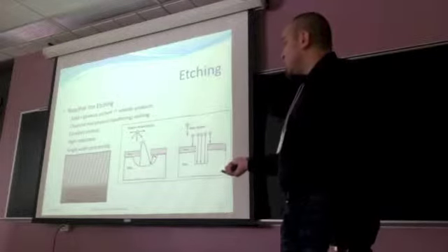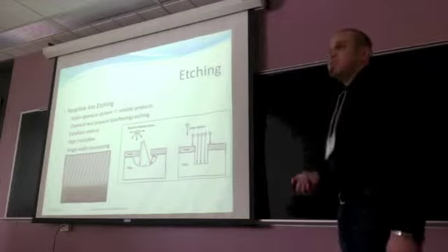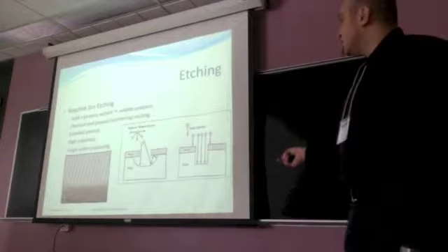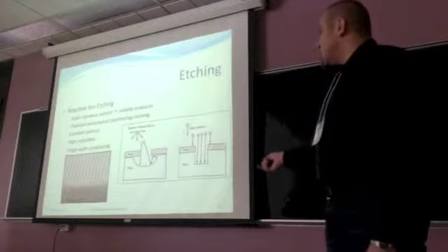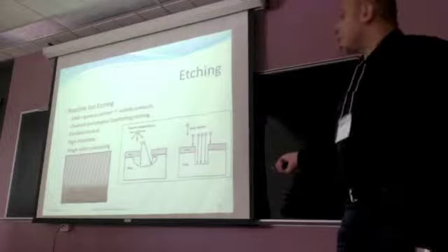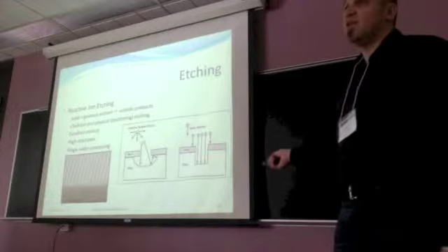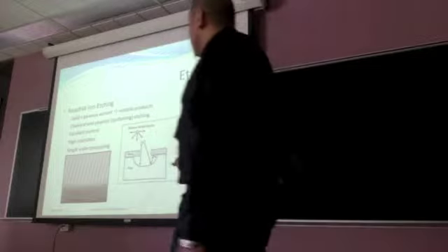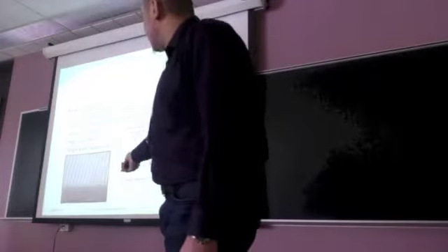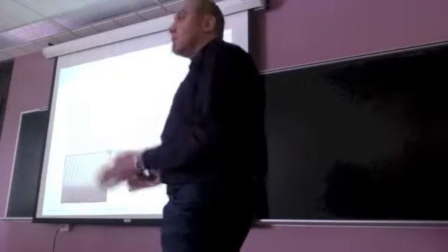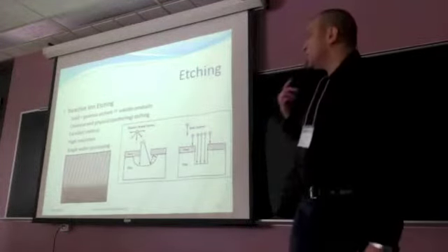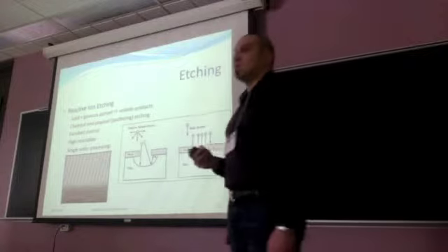And the physical etching is due to ion bombardment of the sample. And this ion bombardment makes the side walls of trenches vertical. And this is what we want. We want high resolution, and this is possible with ion bombardment. So thanks to reactive ion etching, you can get high resolution, and you can see a picture here of arrays of holes with vertical sidewalls. But the main disadvantage of plasma etching is that this is single wafer processing. So only one wafer can be processed at one time.